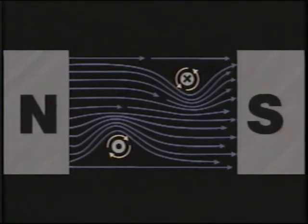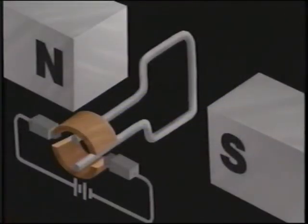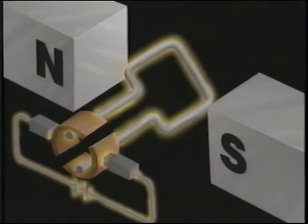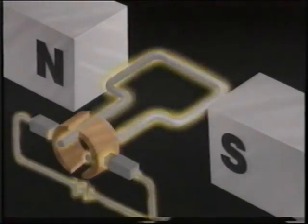As the armature rotates, it becomes perpendicular to the magnetic field and enters the neutral plane where the interaction of the magnetic field is balanced. Here, there is no longer any push on the armature. At this point, the brushes cut current to the armature. However, because of the rotating motion, momentum carries the armature into the opposite field. Once there, the brushes reestablish contact with the commutator, supplying current and thus ensuring the continuous spin of the armature.